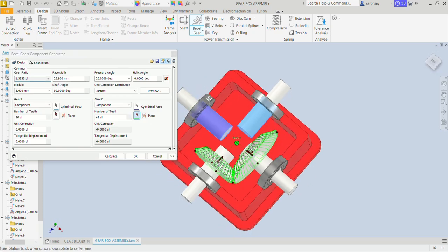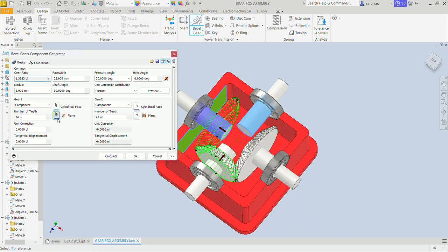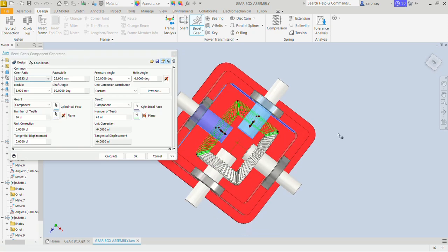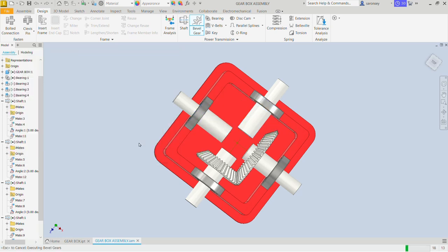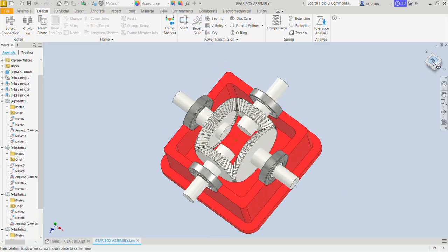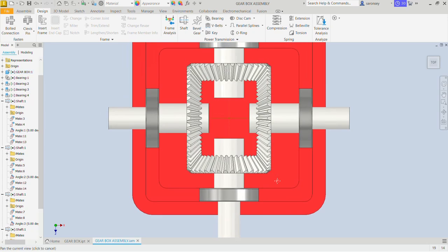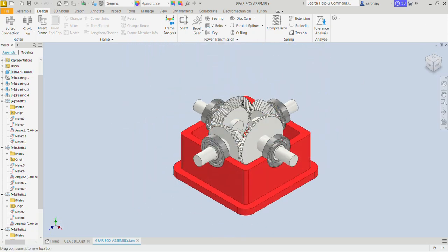And so let's pick for the bigger one this face. And then for the smaller one, I'll click on the plane and we would pick this face. We also see a preview of that. That looks fine. We go ahead and OK. You can OK again. Okay, so that has been neatly done. Let me get the top view. Awesome. I'll get the isometric view. We can even just click and drive to see how that also looks.